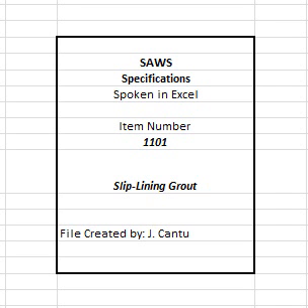1101.4 Construction. 1. The grout mix design and method of installation shall be approved by the engineer prior to beginning operation. Shop drawings and product data shall include, but not be limited to, the following. A. Detailed descriptions of equipment and operational procedures to accomplish the annular grouting operation, including mixing and pumping schedule, grouting pressures, rates of pumping, and methods for monitoring the effectiveness of the grouting.